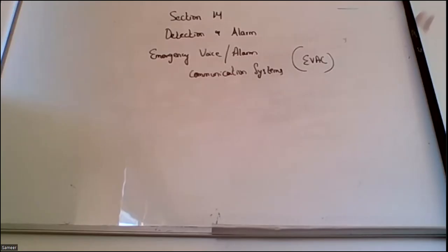Okay, it serves two purposes. To understand the purpose, we have to go back to the history, because it's not a specification based code. This evac is a performance based code. Performance based code means that based on the performances that are affecting the fire systems or the evacuation strategies, a specific requirement is being established.